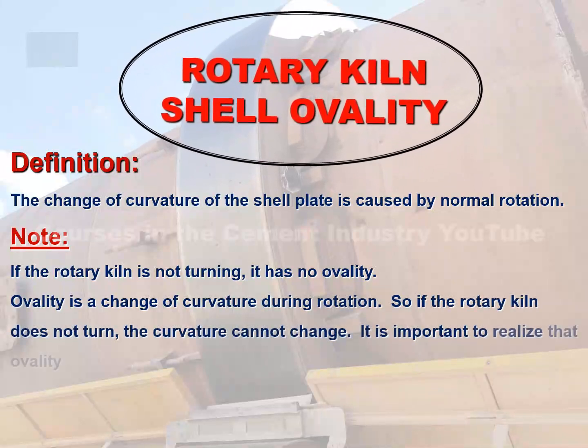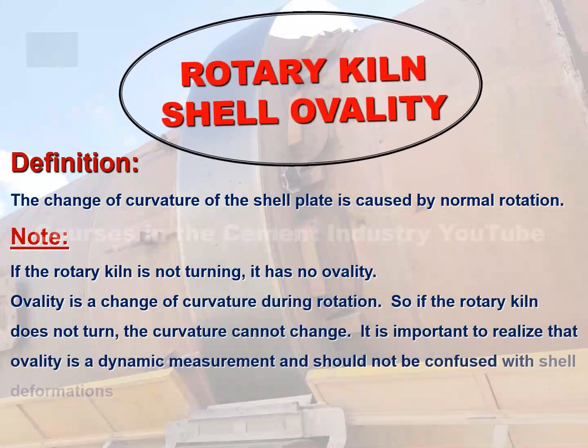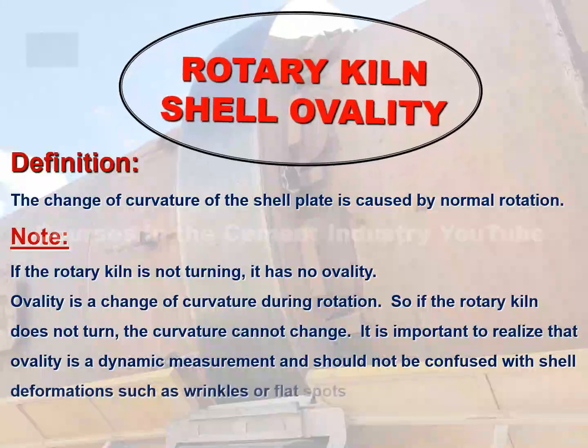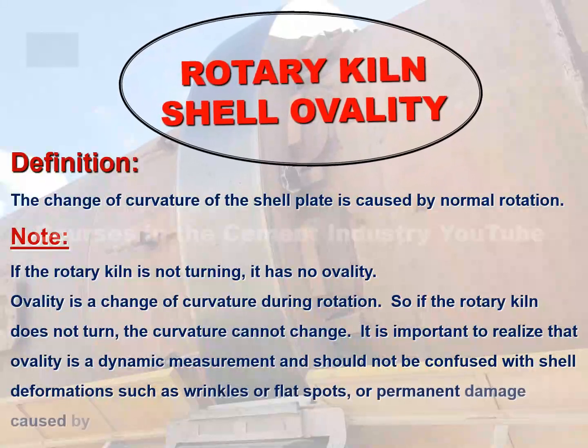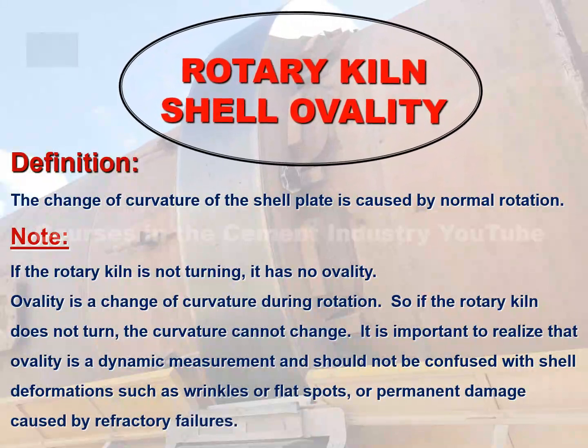It is important to realize that ovality is a dynamic measurement, and should not be confused with shell deformations, such as wrinkles, or flat spots, or permanent damage caused by refractory failures.